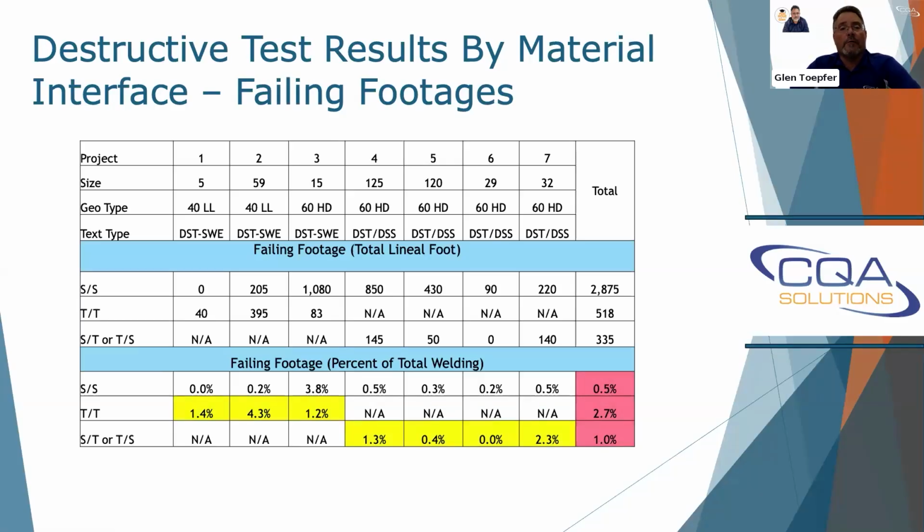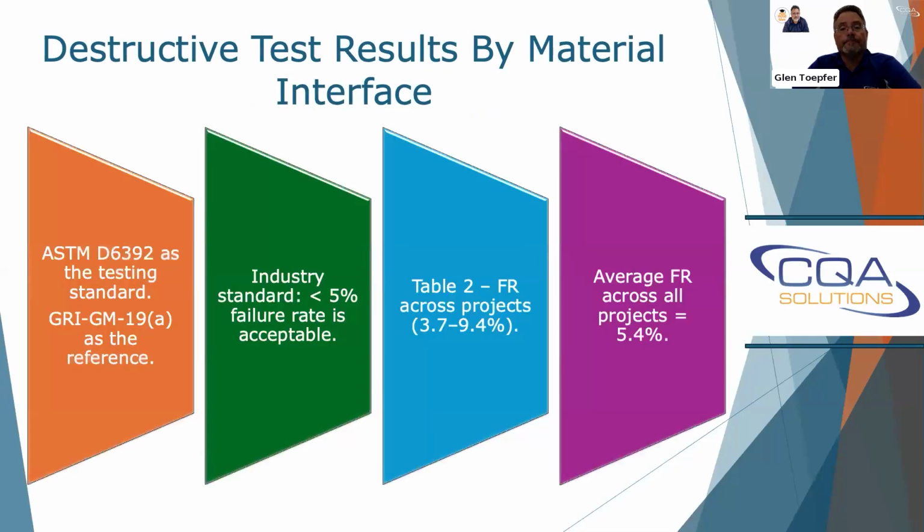It's going to bound and pass. The textured, any textured interface, on the other hand, is going to propagate more. So your failure is going to run a little bit longer. It's not going to just be bound, 20 feet, 10 feet in each direction from your failure. More than likely, when you encounter one of these, it's going to propagate further. So that's another finding to keep in mind, and another reason behind my ultimate recommendation of targeting interfaces.